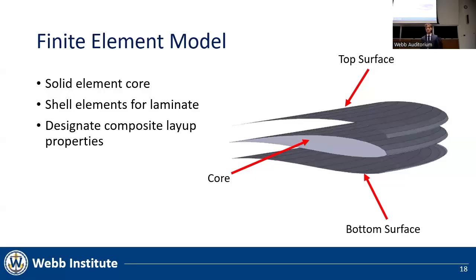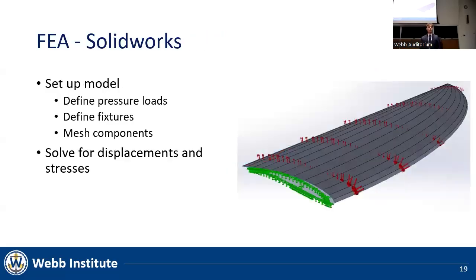With just these 3 bonded elements, we now have a representative model of the hydrofoil that we can use for finite element analysis. Before we can hit run on the analysis, however, there are still some things we need to set up. We need to create a pressure load and distribute it according to the best fit equation from MATLAB. We also need to fully fix the root of the foil as if it was attached to the mast of a T-foil arrangement. Finally, we need to mesh each element we created.